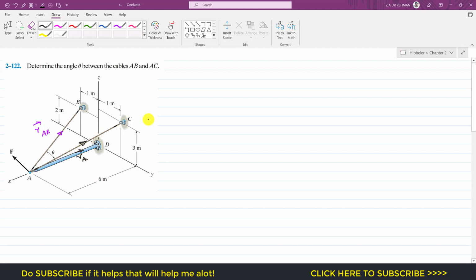So using the dot product, we can find the angle between both of these cables, right? If I take the dot product of these two position vectors, RAB dot RAC, this will be equal to the magnitude of RAB and the magnitude of RAC cos of theta. From this we can say that cos of theta is equal to RAB, the position vector, dot product with RAC, the position vector, divided by the product of their corresponding magnitudes.